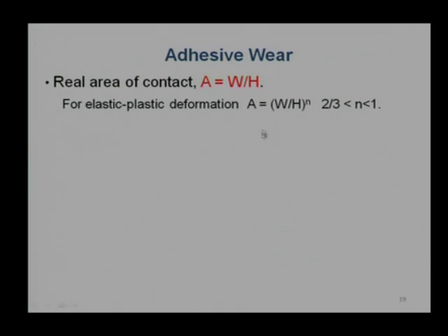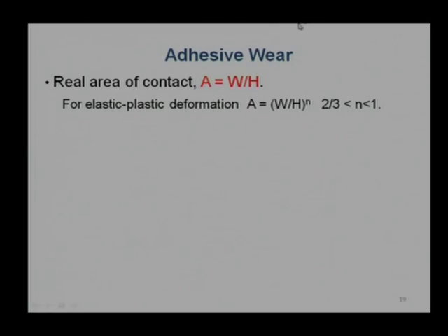However, the basic assumption is that there is a plastic deformation. That is why the H has been used. H is a flow stress. It allows the material to resist up to this limit, and if you increase the normal pressure more than that, then it will allow the surface to penetrate easily. So, that is why H is a flow stress, and this area A is equal to W by H is valid only for a plastic weld, or a weld made after the plastic deformation.